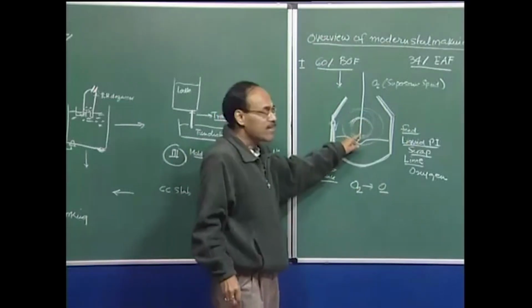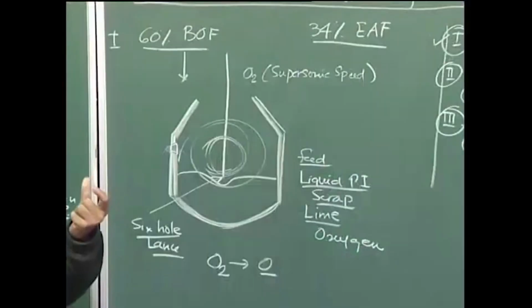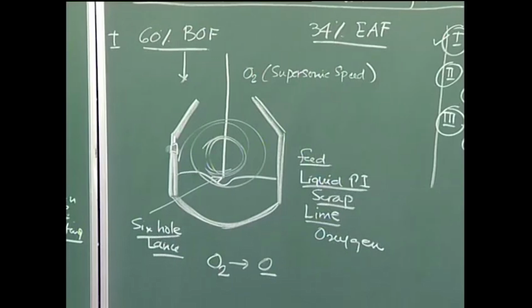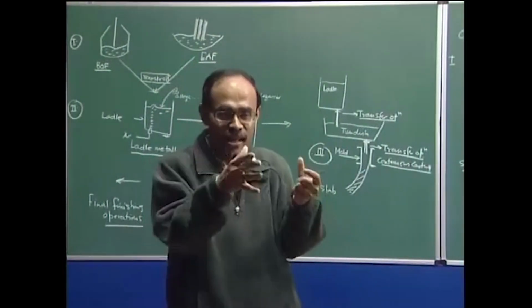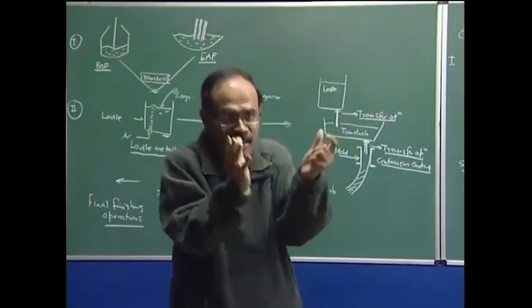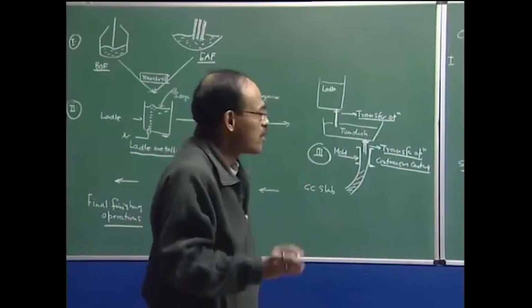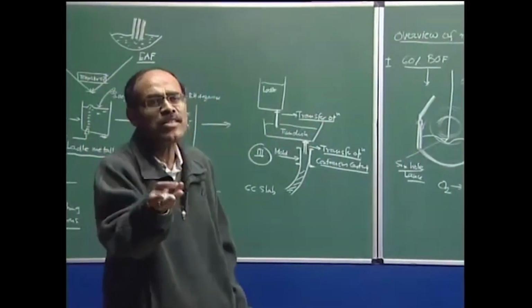So, you create here a mixture of gas, slag and metal droplets, and you increase the surface area. As I have mentioned, and you will also know in greater detail, steel making reactions are mostly mass transport controlled heterogeneous chemical reactions, so they depend on the interfacial area. So, the finer the droplets of metal created, the better, because where is the carbon sitting, where is the sulfur sitting, where is the phosphorus sitting?